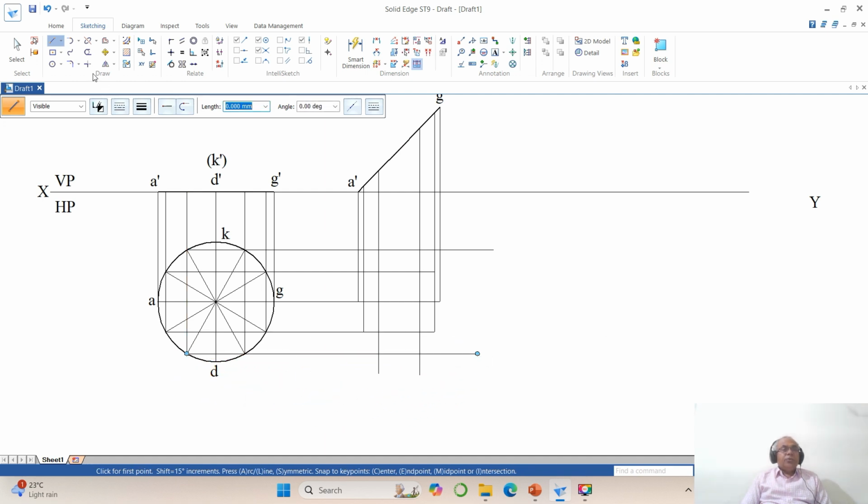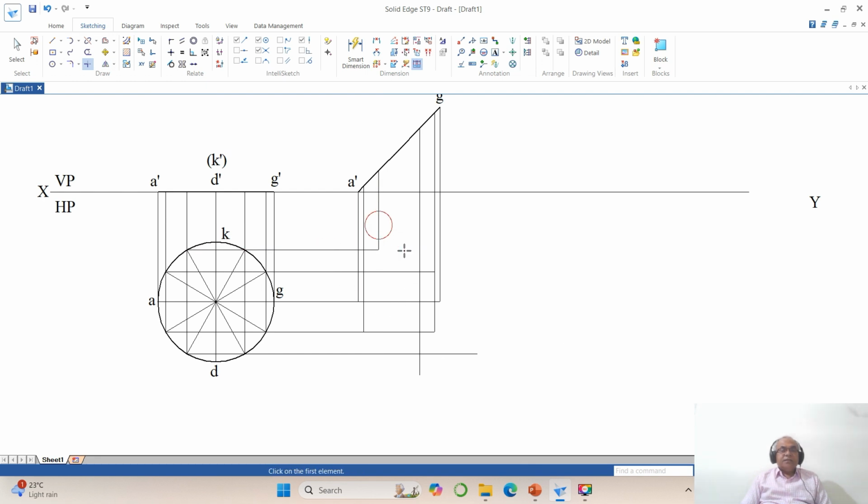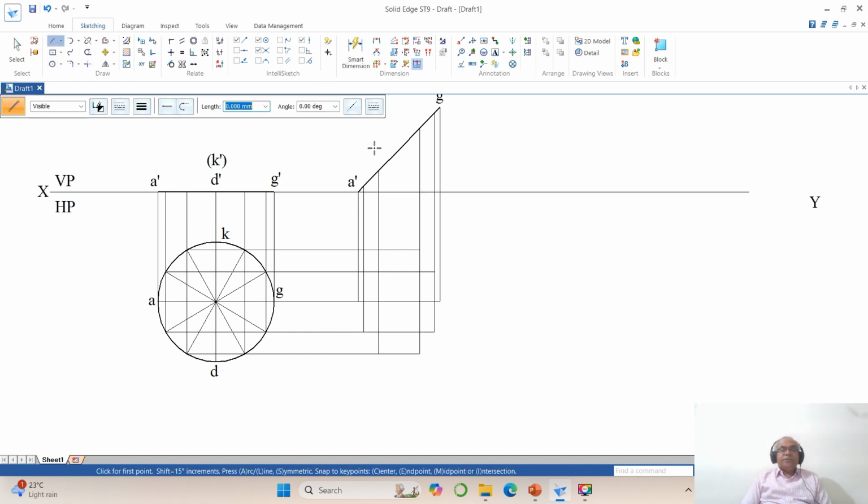Then again go to trim corner between this line and this, between this line and this line. Similarly between this line and this, and also between these two. Do one by one. Don't try to project all the points and then start working on it. Then you will get confused. So again you go to end point and you take this. Similarly from here you take the end point.